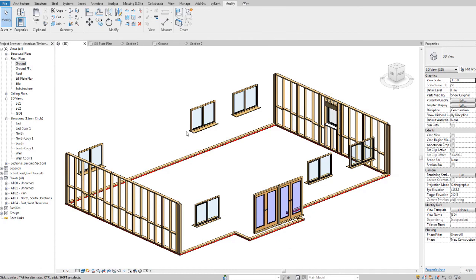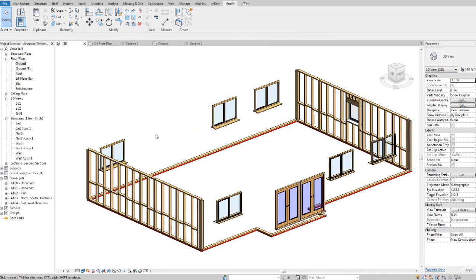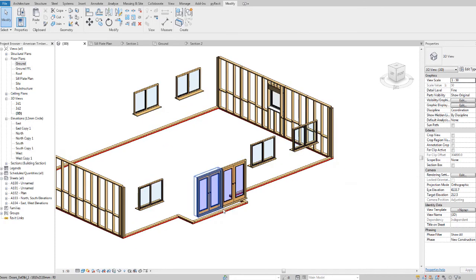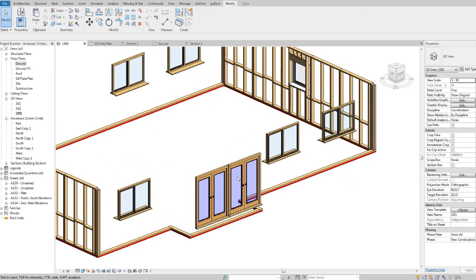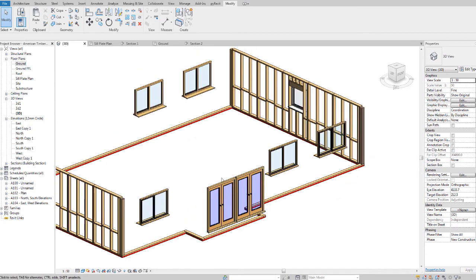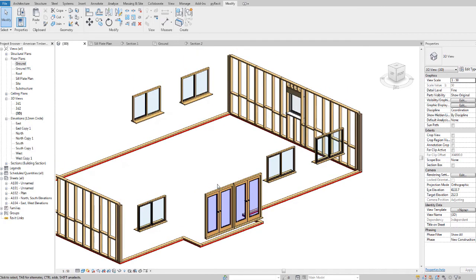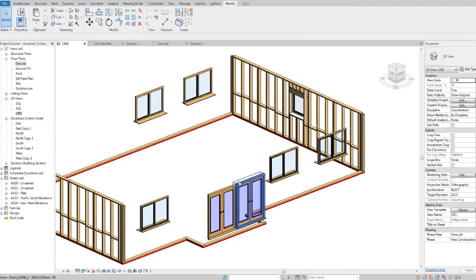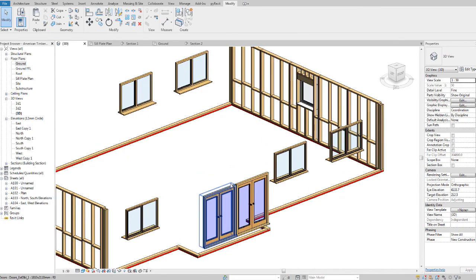For this side, we're going to do the exact same that we did here, just 3 times. And for this side and for this side. But for this, we're going to do something different. We're going to add something on the top called a flitch plate, or a flitch lintel. So that's a lintel that's harder than normal.